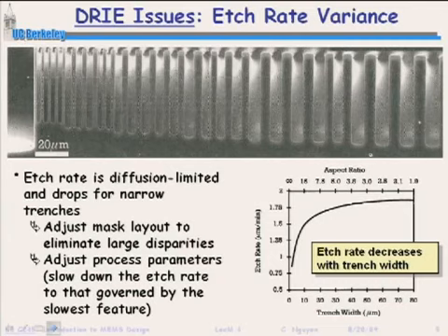Okay, so get a dummy wafer with a dummy layer of that film you want to etch. Use your mask on that dummy wafer and etch it for a certain amount of time, maybe 30 seconds. Measure the thickness before and after that etch, and there you determine your etch rate for that particular mask. If you use that etcher again with a different mask, you've got to determine the etch rate again. Right? Do not trust someone else's etch rate because it's going to be different from yours just because your mask is different.